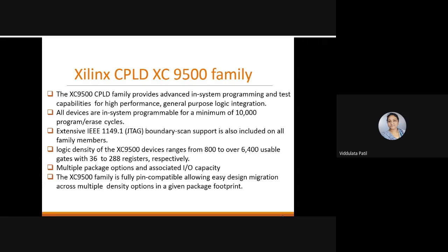Then the density of the XC9500 devices ranges from 800 to over 6400 usable gates. That means the logic gates available on these XC95 devices range from about 800 to 6400 usable gates. Also, there are 36 to 288 registers.